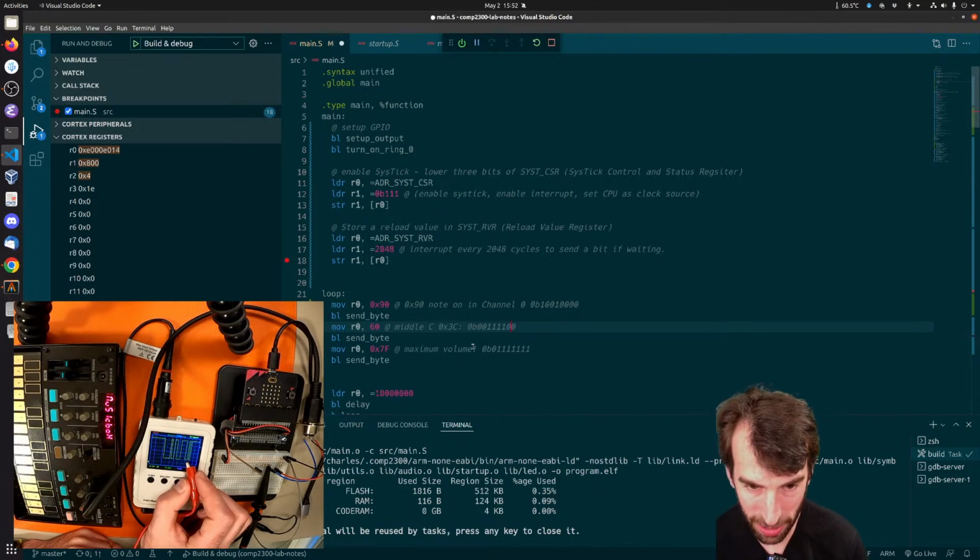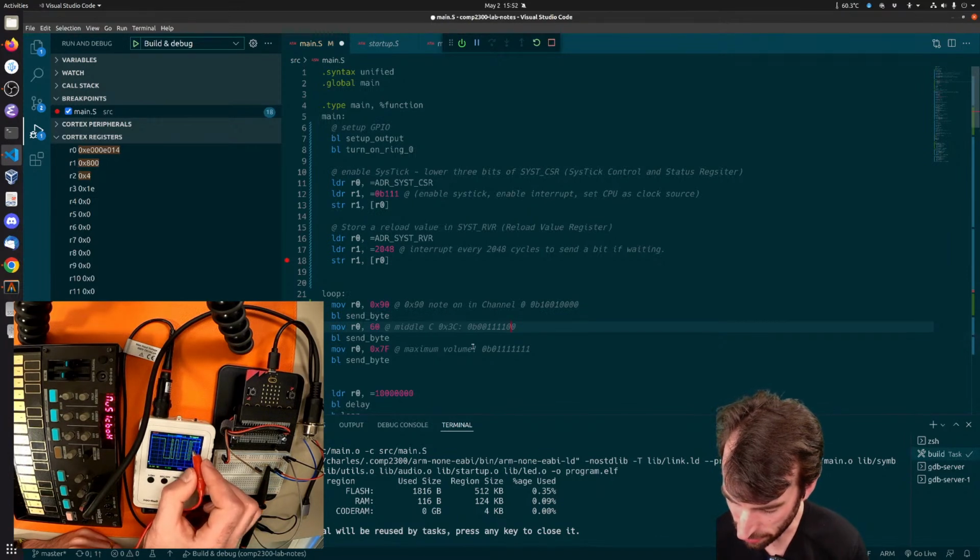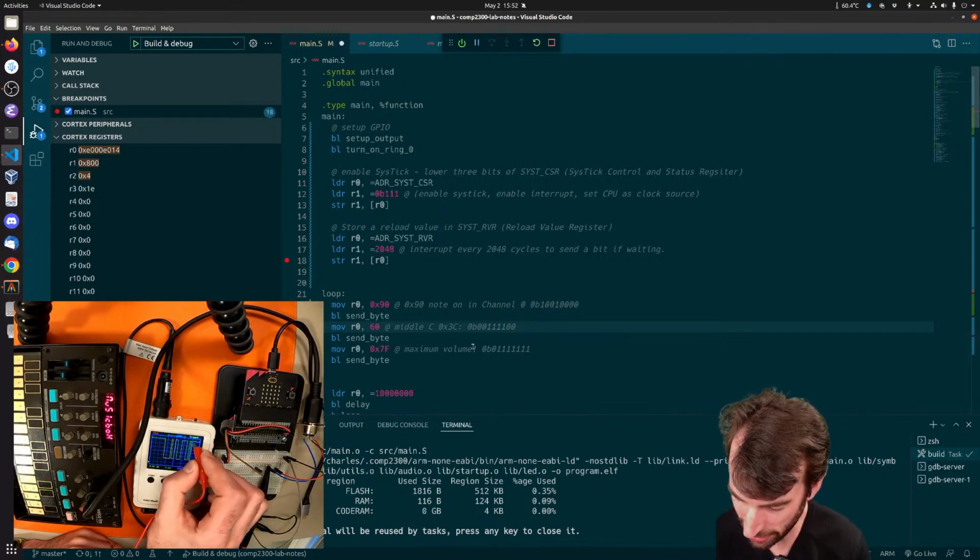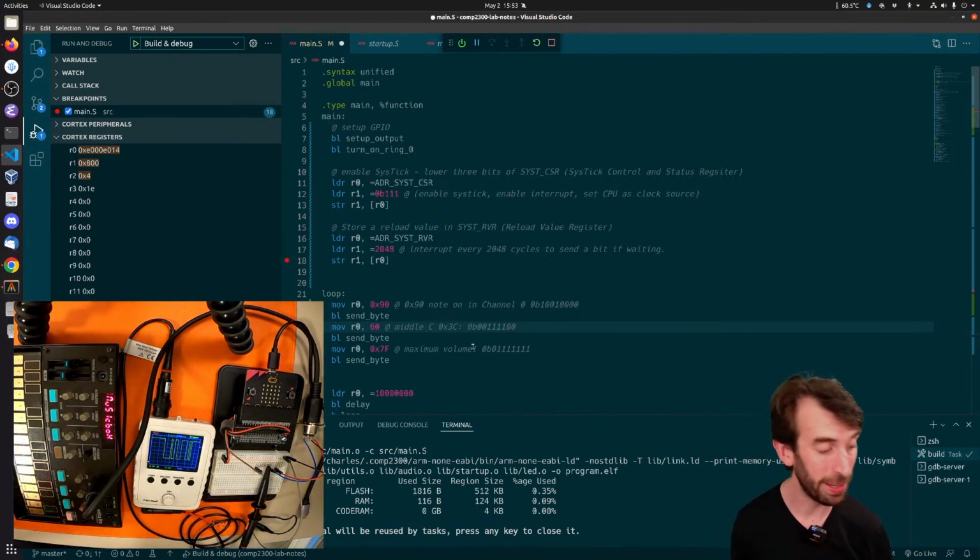And then we've got our 7F, which is just going to be 1 0 there. That's our stop bit for the next byte. Start bit 1 0, and then 1s until the end of the frame. And that's our 3 MIDI frames.